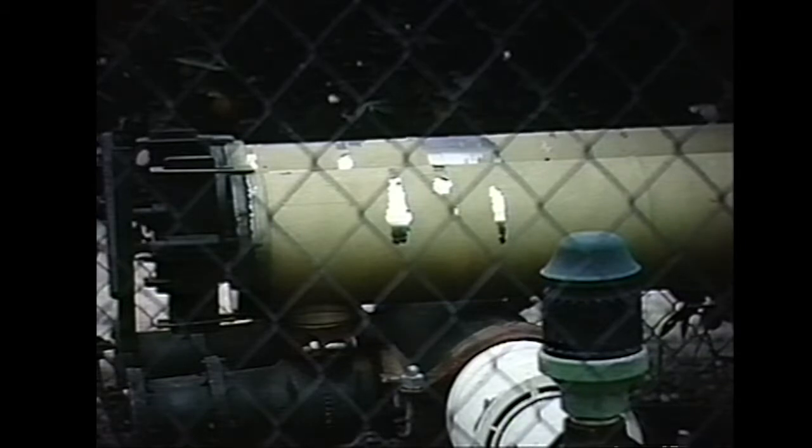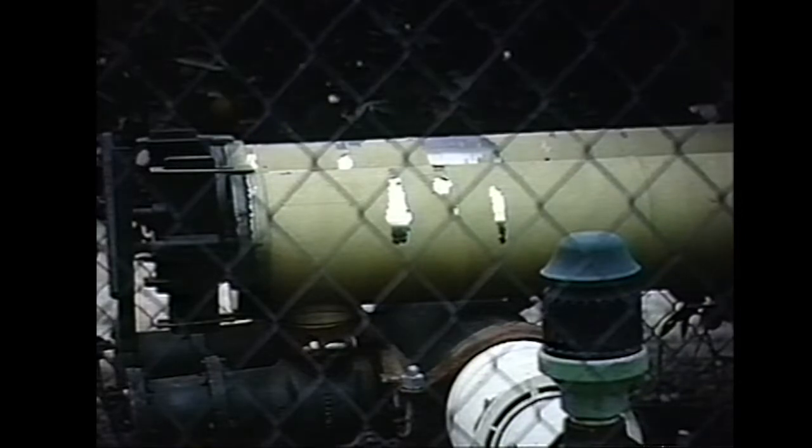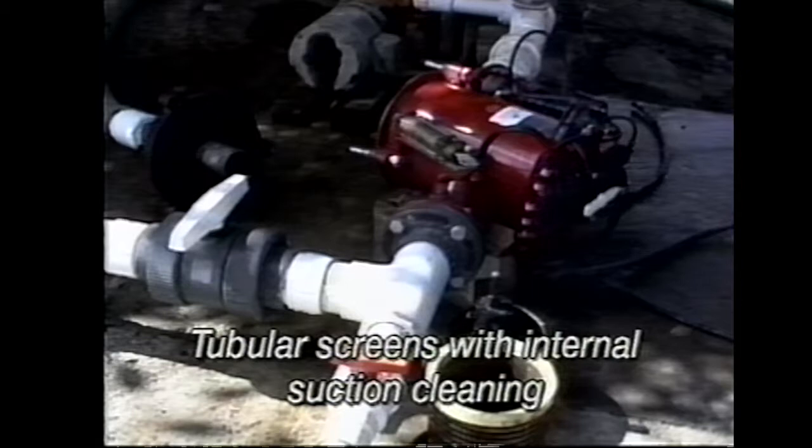The screen should be easy to access and have a slow release lid, as should all filters. Operators should be able to remove the screen without dropping the dirt into the outlet hole of the device. Some manufacturers have a special design which appears to be a tubular screen, but which has an internal rotating self-cleaning mechanism to overcome the capacity problem associated with standard tubular screens.